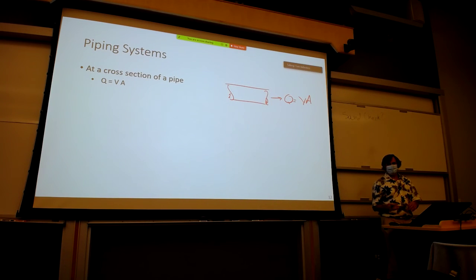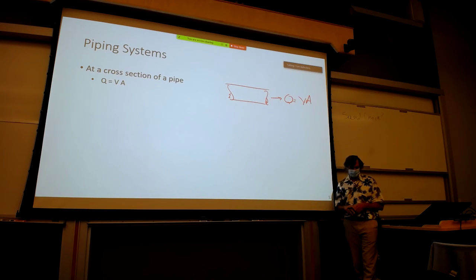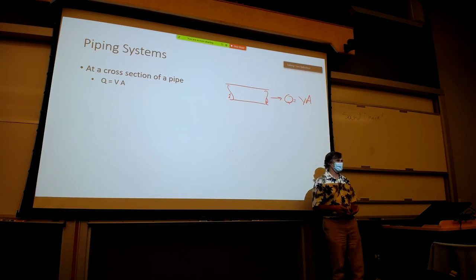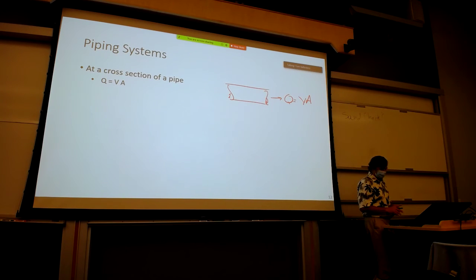So when you hear something that says it's a 6-inch pipe, that's actually not the inside diameter of the pipe. That's what we call the pipe. The inside diameter is something close to that. We're going to get into that in future lectures. For now, when you hear it's a 6-inch diameter pipe, you are to assume that that's the inside diameter, or ID as we call it.